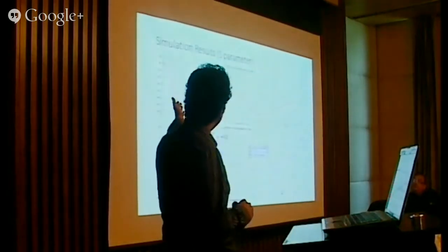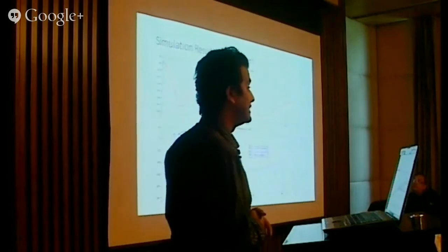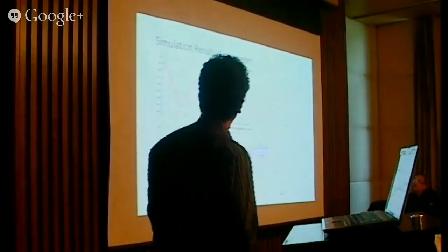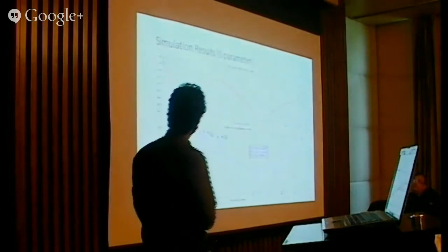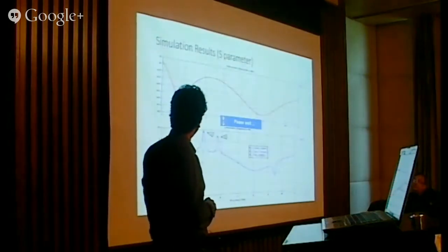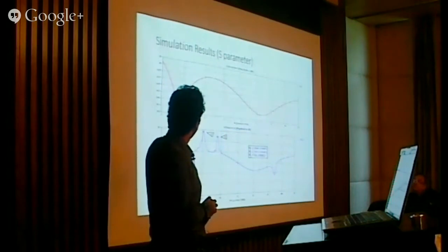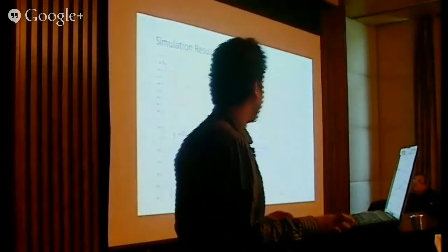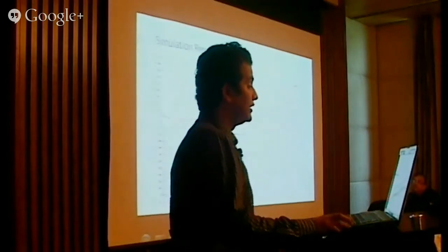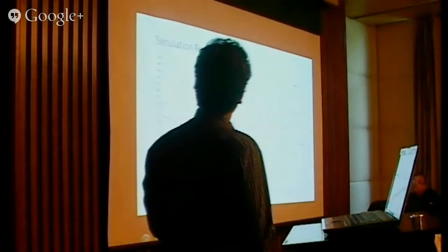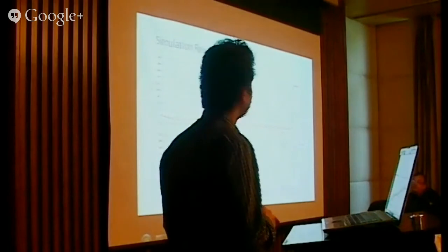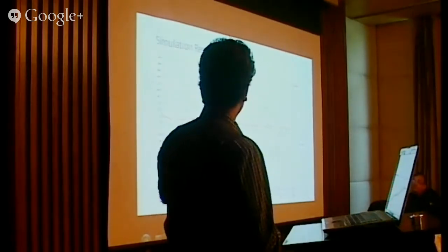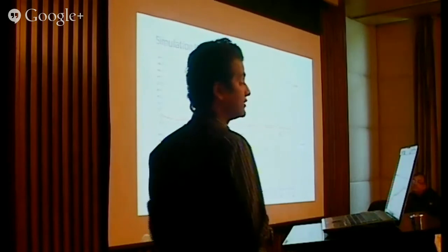The picture shows the VSWR of the antenna without any source. And the next picture shows that three notches have been created where the S parameter goes above 10, hence causing the antenna to not radiate at those frequencies. This is the same with the VSWR. The upper picture shows the VSWR of the original design, and this is after the modifications of the actual source.